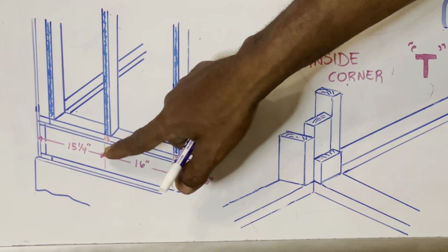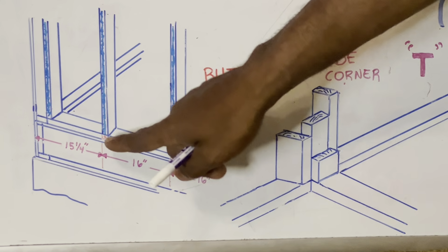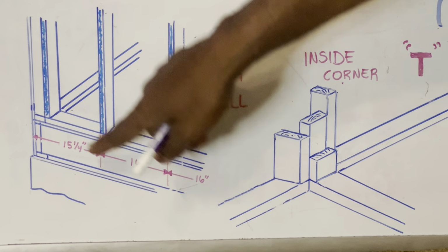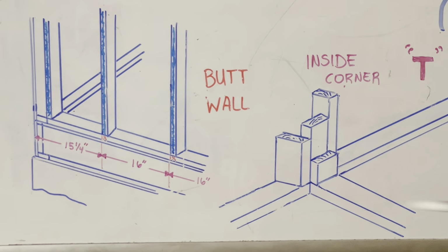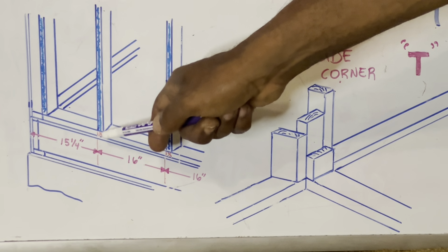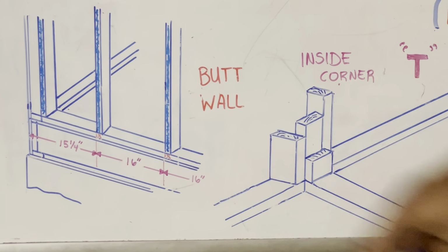Okay, put your nail right there, then get your tape measure up, connect it to that nail, then pull it out. Then you're gonna go 16 on center. Okay, and look right here, the same thing's happening. Your X is to the right of your line right there, see?